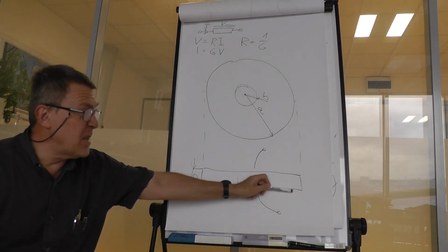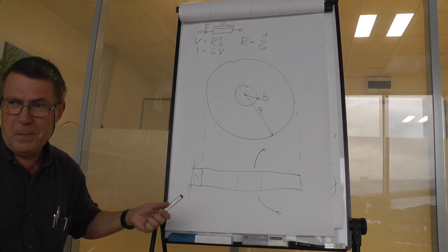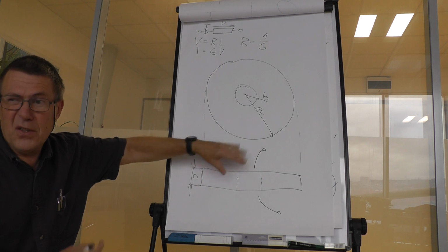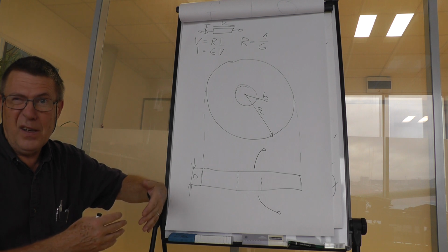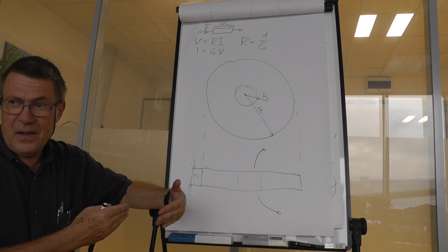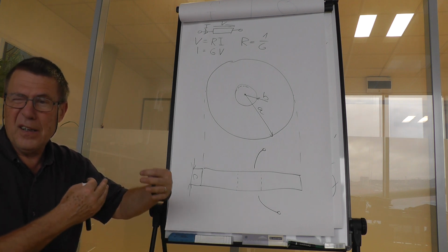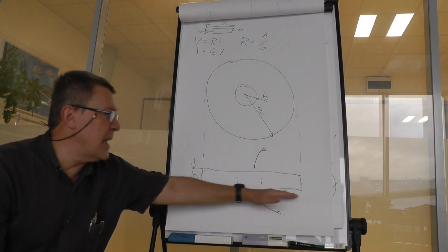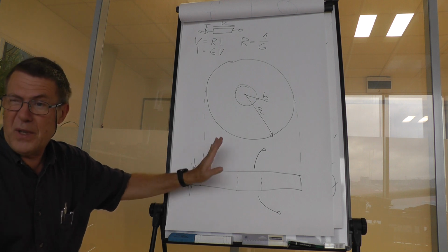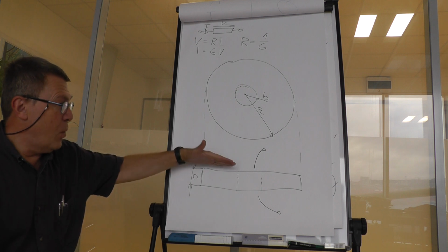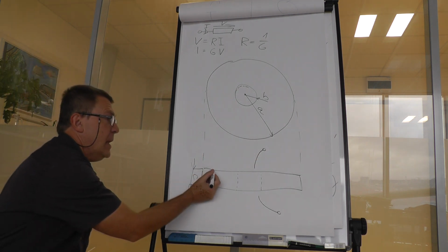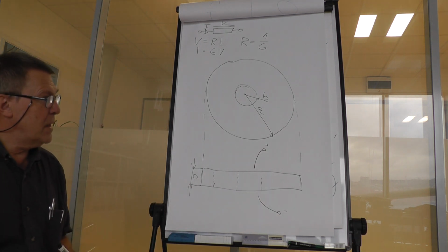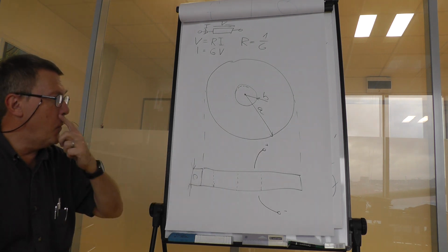Those two metallic electrodes, upstairs and downstairs, would create equipotentials. They are much more conductive than the rest, so there would be no tangential field, because if it had somehow happened, it would exactly at that moment drag charges, and those charges would move as long as they would cancel the field. So a metallic surface is an equipotential, and we do not have to bother with tangential field components there. Now we have something which would create a homogeneous field where the current would flow from upstairs to downstairs, and this is the plus and minus pole of the feeding voltage or current.